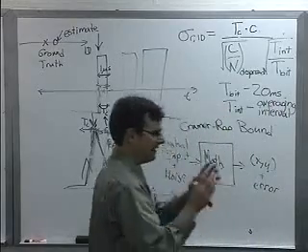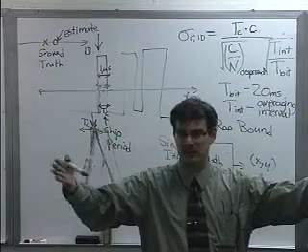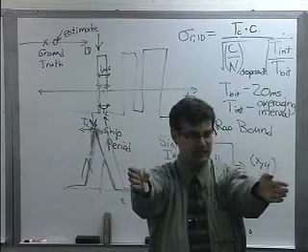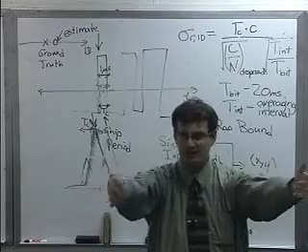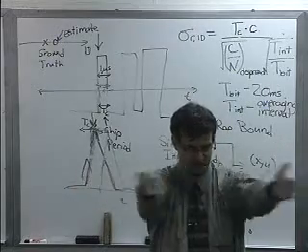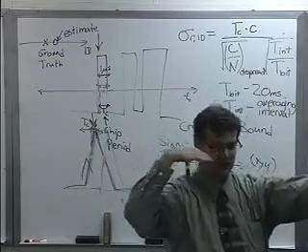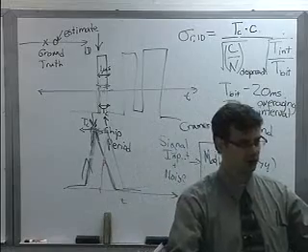Well, technically, we know in this class that an antenna array gets this big in space, which means a pattern is going to be this big in a pattern domain. So, if you get a signal in that pattern, then you'd expect this to be your angular error. However, there are these other techniques where you can look at the signal and say, okay, it's going to have a plane wave structure.